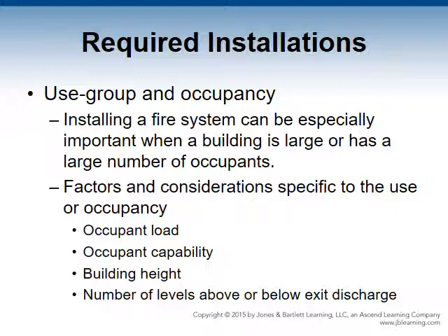Factors and considerations may be specific to the use or occupancy. All of these meet a specific threshold before the installation requirement is valid or before an exception changes the requirement, such as occupancy load, egress capability, height, and the number of levels below or above exit discharge.